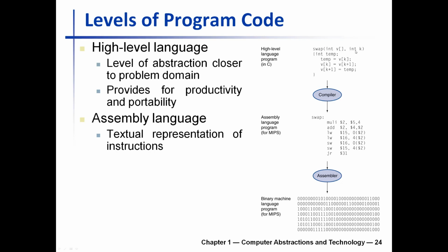Those two are given in these 2 variables, right? So there must be some sort of a convention in the instruction set saying the arguments to the function should be passed through registers number 4 and 5. Register number 4 is holding the first argument, and register number 5 is holding the second argument.